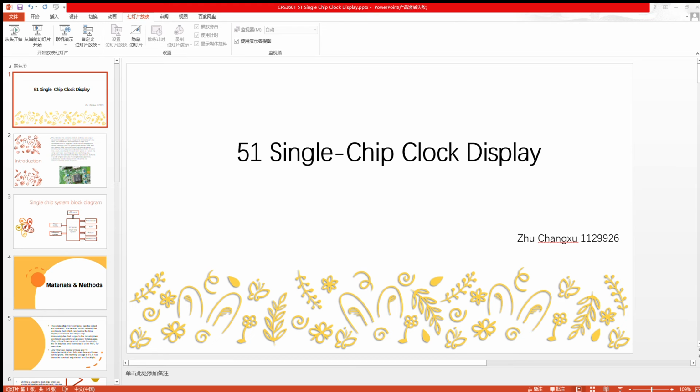From the picture, we can see the leftmost key. If we press that function key to select the mode, it updates the interface on the LCD, including time display, date display, and clock. The second key is to select and flash the current cursor position. After pressing several times, the cursor will continue to jump in sequence to the next position.